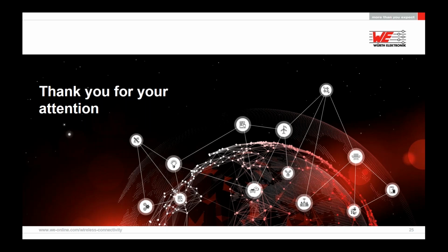One last comment on my side is to avoid mounting the antenna straight or flush onto a housing or anything which could be conductive or a ground plane. Antennas like to have some free space around them, so even with the PCB and chip antennas, try to keep them clear from the wall of the housing and so on. There is a lot of theory available in books and on the internet.